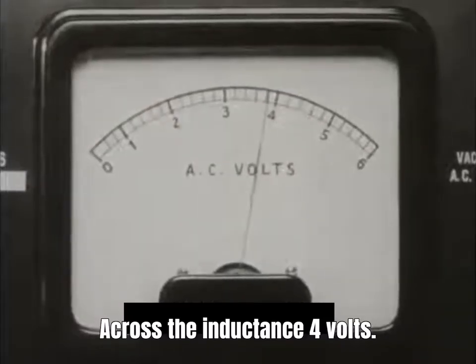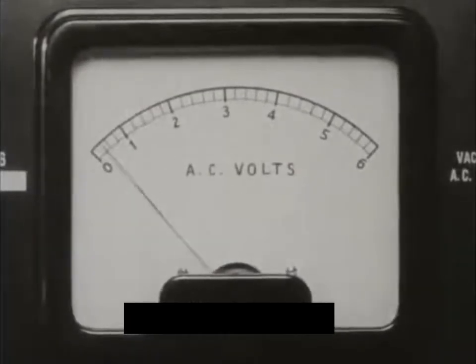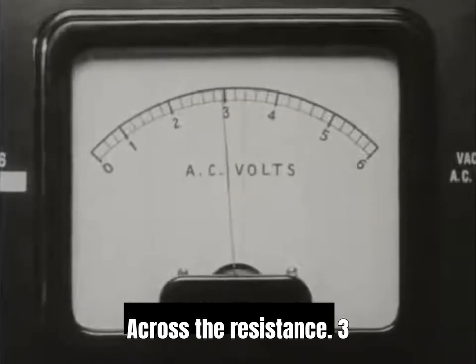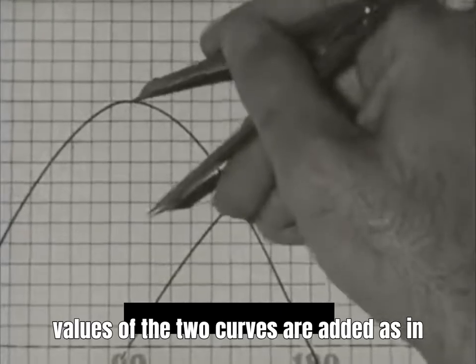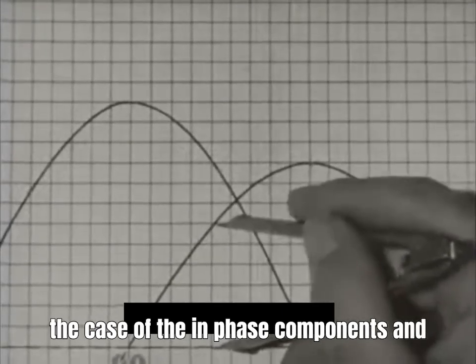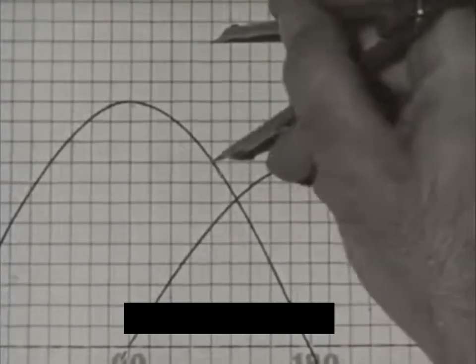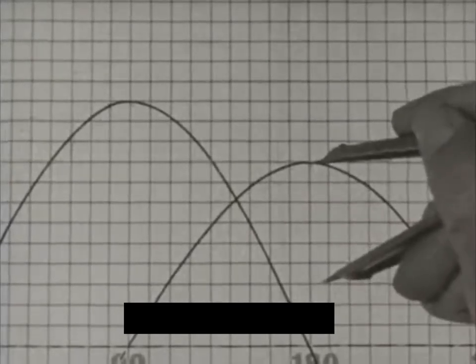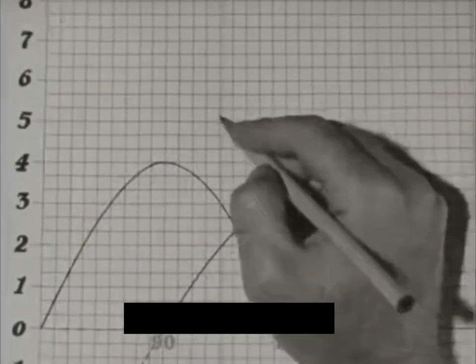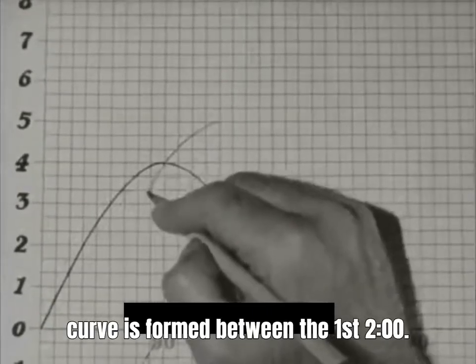Note that these values are the same as the voltage drops which were measured a few moments ago. Across the inductance, 4 volts. Across the resistance, 3 volts. Now the instantaneous values of the two curves are added as in the case of the in-phase components, and the resultant values are plotted on the graph. When these points are connected, a new curve is formed between the first two.